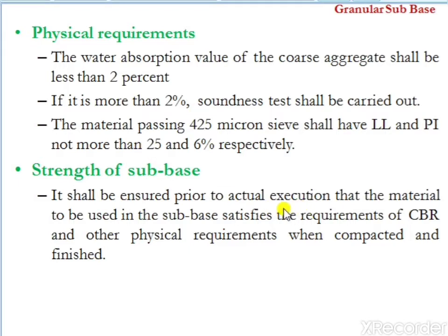So before the material is used in the construction of sub base, it should be tested in the laboratory or in the field. When we test the materials in the laboratory, the materials used in the construction of subbase should satisfy the requirement of CBR and other physical requirements.